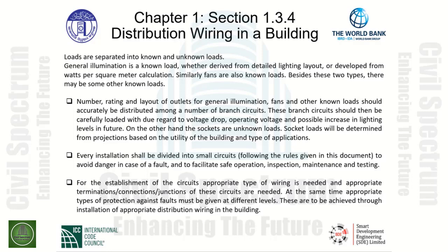Number, rating, and layout of outlets for general illumination, fan, and other known loads should be accurately distributed among a number of branch circuits. These branch circuits should then be carefully loaded with due regard to voltage drop, operating voltage, and possible increase in lighting levels in the future.